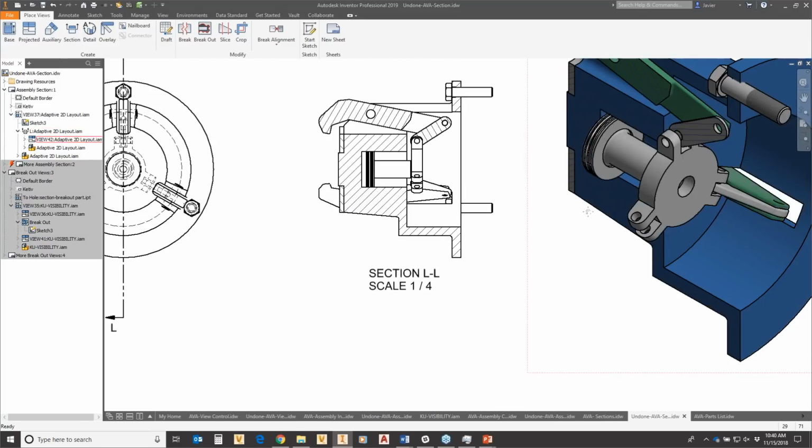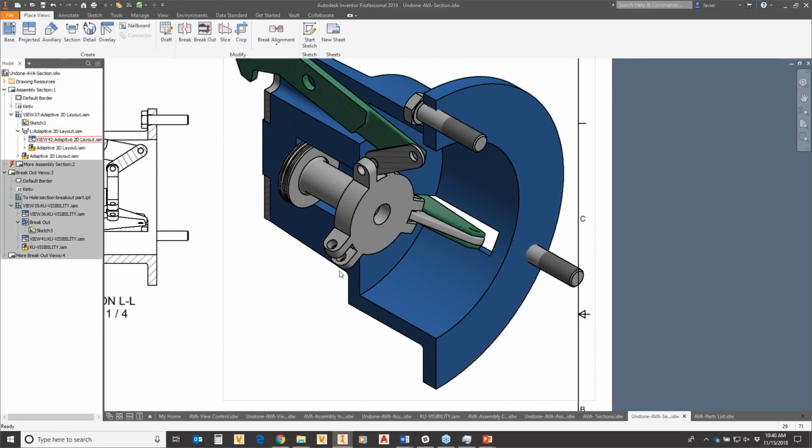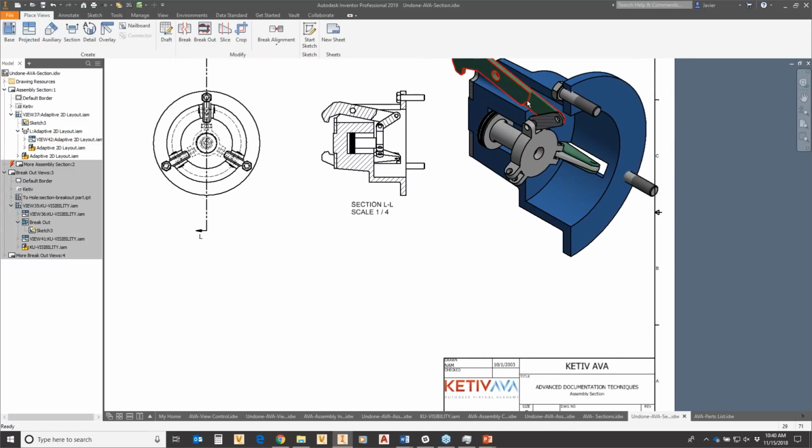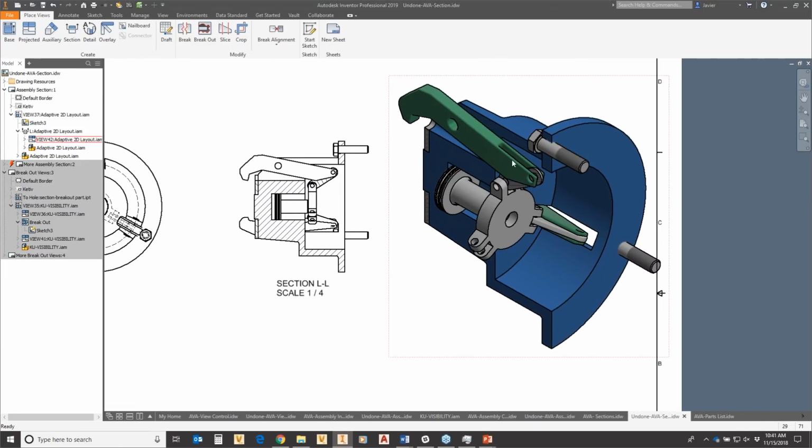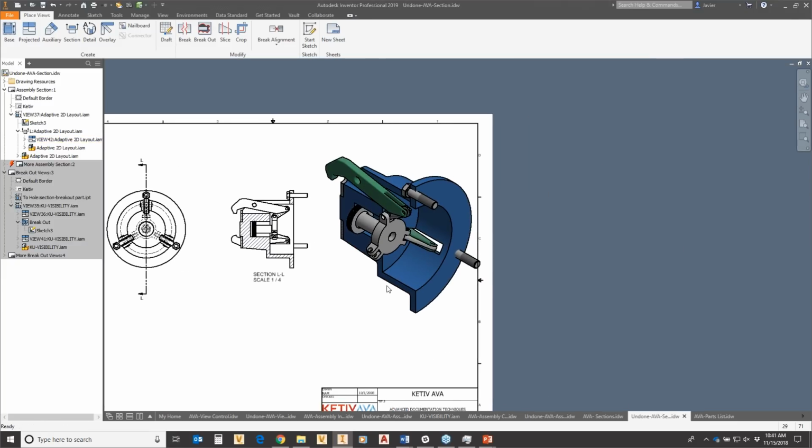It's now whole, and when I look over here, I get to see this complete. I could go on to quite a few other parts and do the same thing and tell them to show up complete. So be careful when you're doing this, just because sometimes you'll pick the hatch, even though you're in part mode. You want to make sure you pick visible edges, right click, and tell it not to section that entire part. Okay, so parts whole, right? Not sectioned off. So you get some control over that.